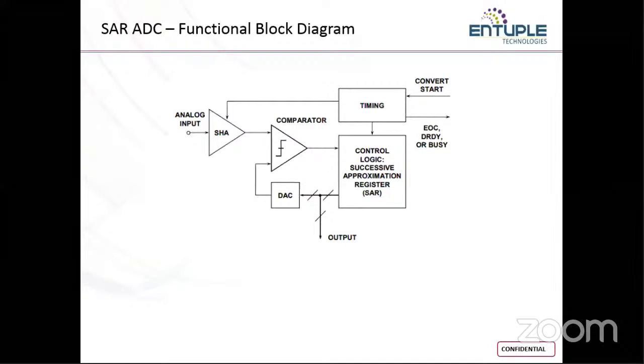Or what we can do is just give an analog voltage source and vary between 3 or 4 different values of voltages, starting from 0 level, mid level, and full scale level. That is what we had done on Cadence.